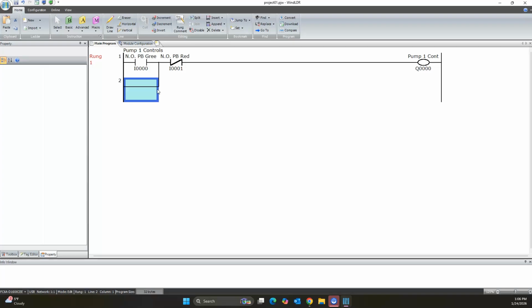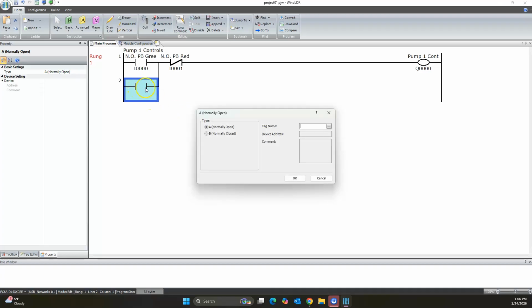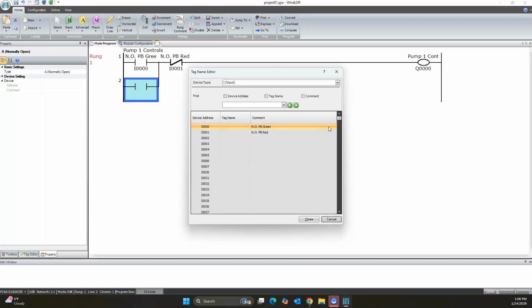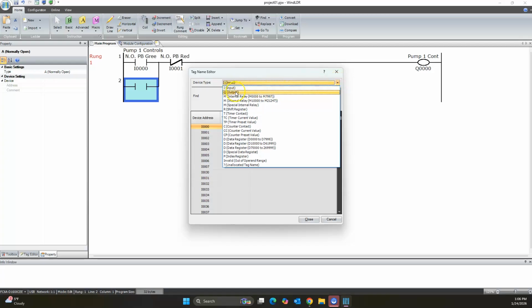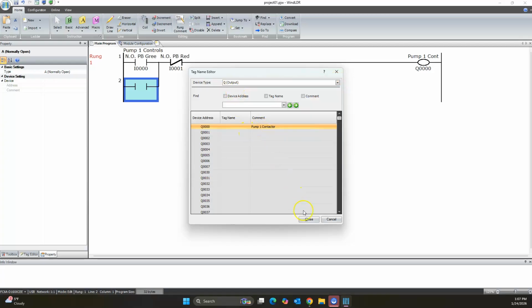Normally we would use auxiliary contacts on a contactor with relay-based ladder logic to make this latch work. But we can actually use a virtual sort of relay to establish a latching circuit just like we would with relay-based ladder logic. So I'm going to grab that normally open instruction again, and now I'm going to double click it to open up this property box, and I'm actually going to associate this instruction with our output just like we would in